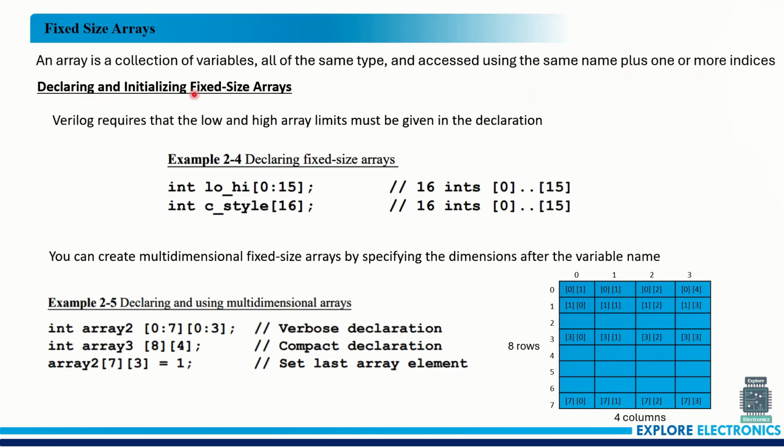There are different types of arrays in SystemVerilog. There are fixed-size arrays, there are multidimensional arrays, there are packed arrays and unpacked arrays also. So in Verilog, it requires low and high array limits to mention the size of the array.